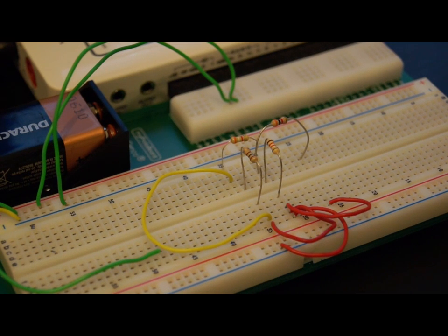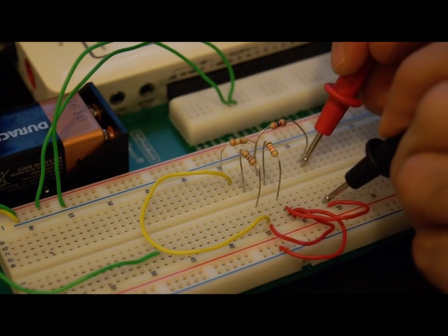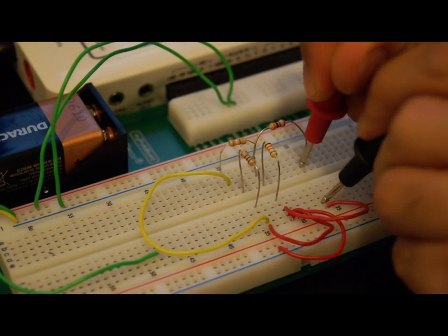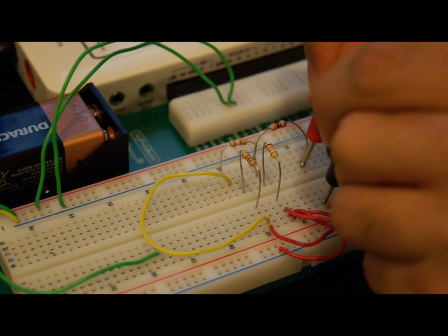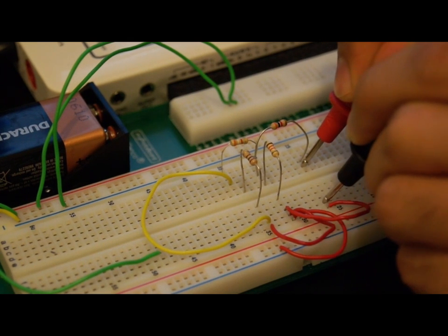We then bring up our digital multimeter on our computer, set it to ohms, run it continuously, and now if we place our nodes across resistor 4, we will get our Thevenin resistance, which is 3.9 kilo ohms.